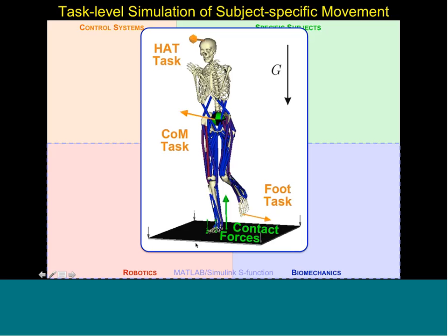I want you to look at these green arrows on the foot-ground contact. There's no attachment between the foot and ground. There's contact modeling being done through OpenSim Hunt and Crossley spheres to generate realistic ground reaction forces. This is required for most predictive simulation because we don't have access to all the experimental data, and we want to be able to generate those ground reaction forces to hold our models.